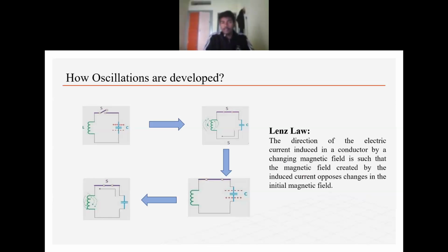Now oscillations are being formed, but in the real case, the oscillations formed are actually damped oscillations due to the resistance provided by the wires and so on. So to reduce these damped oscillations and make them the required undamped oscillations, we'll be giving a continuous input, which is a DC current, and we'll be attaching wires and taking this circuit as the load, so that the AC current generated in this load can be taken out from these points. So we'll be giving a continuous DC current, and that DC current will be converted into AC current by the oscillations, and then we can take it out.